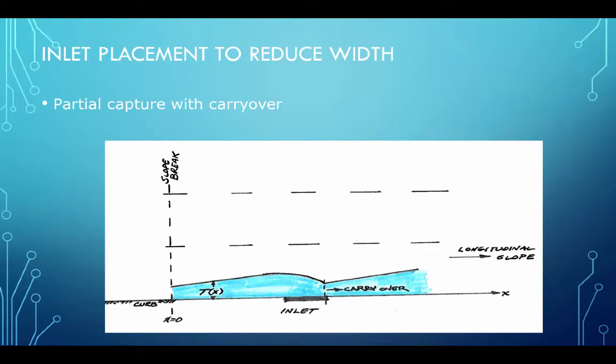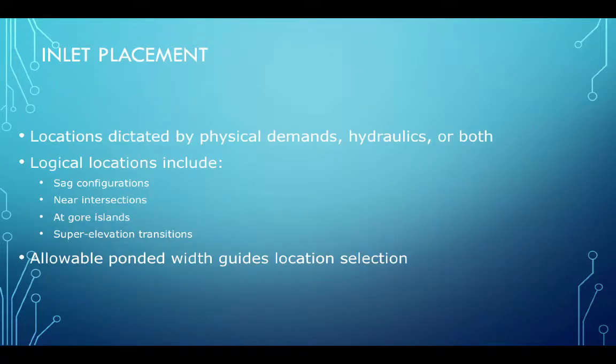Sometimes it's desirable or necessary to allow carryover. That's fine, you need to design for it. And the locations are ultimately dictated by physical demands, hydraulics, or both. Logical locations are sag locations. That's almost absolutely necessary. Near intersections, at gore islands, and at super elevation transitions.